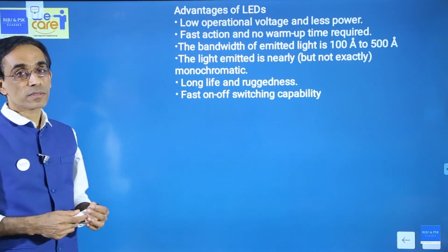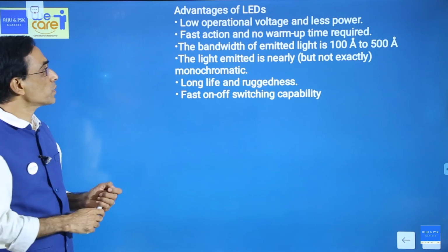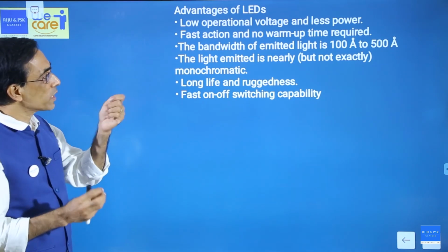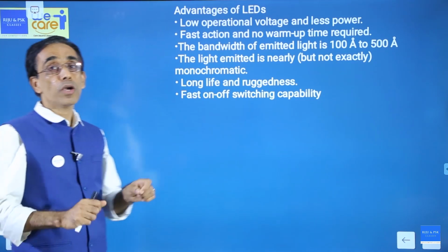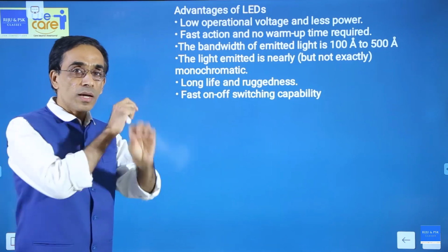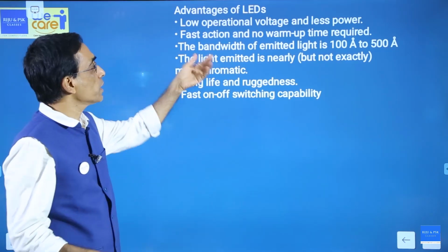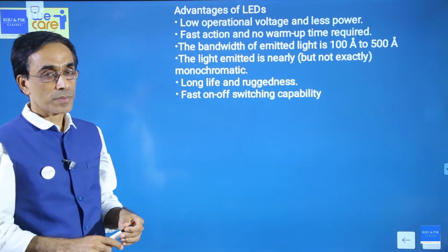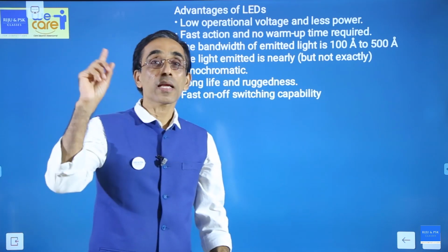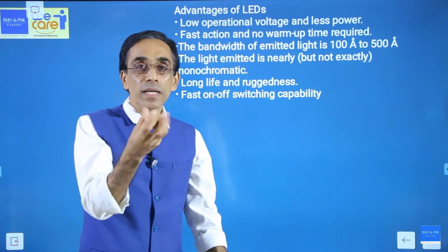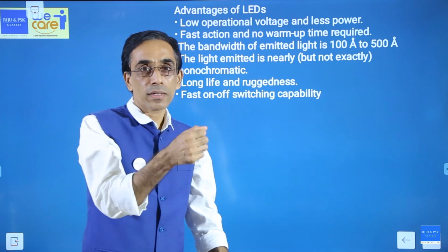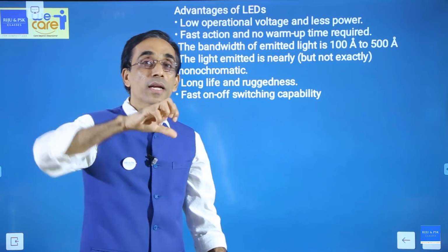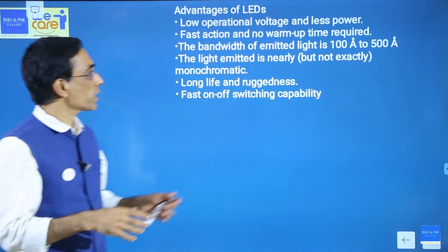What are the advantages? You don't get any numericals from this one. Advantages: they consume a very small amount of power and they are almost instantaneous. You turn it on, and at that instant they come up bright. There is no warm up period. You must have seen that street lights which use a sodium vapor lamp have a warm up period. The moment they are turned on, they wouldn't produce light. They take some amount of time. But this will not take any time at all.